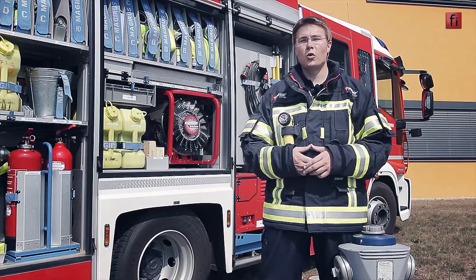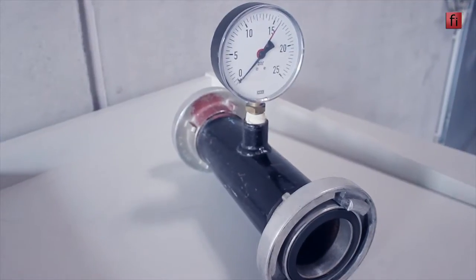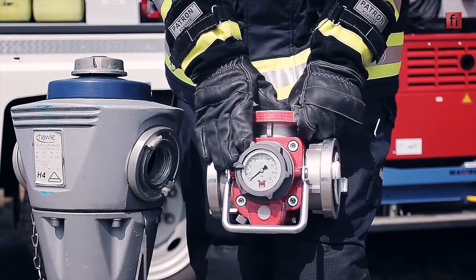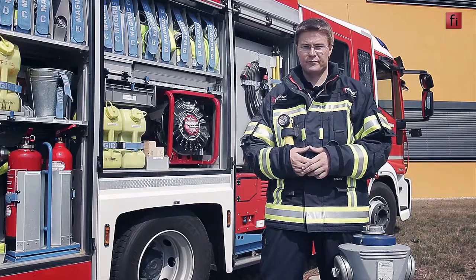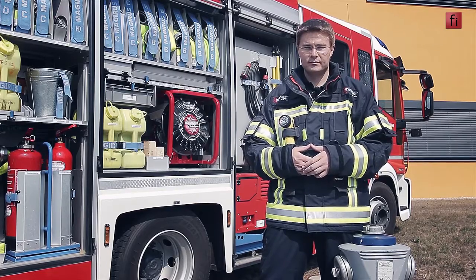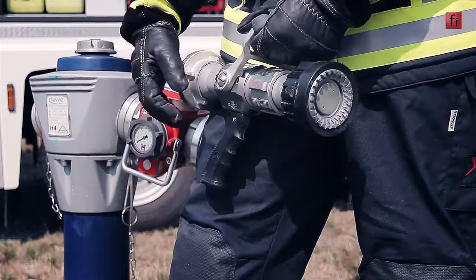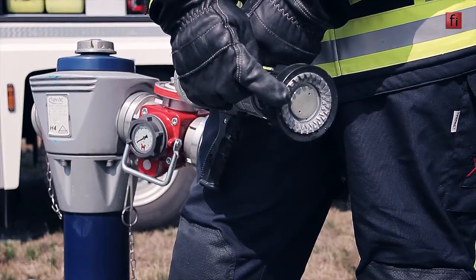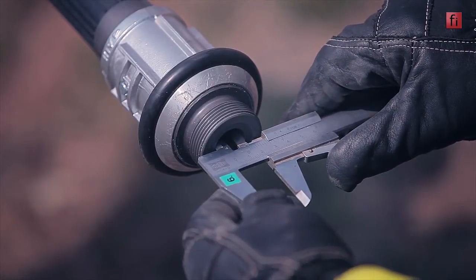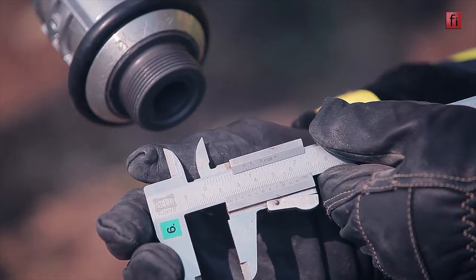The first one is the more exact one. Here you can use a big pipe with a pressure manometer on it, or you have another facility to measure it like this. But it's important to have a large inner diameter. Now, connect a nozzle onto that. But do not use a fork nozzle, because we have to meter the inner diameter of the nozzle. In this case, we have 0.9 inches.